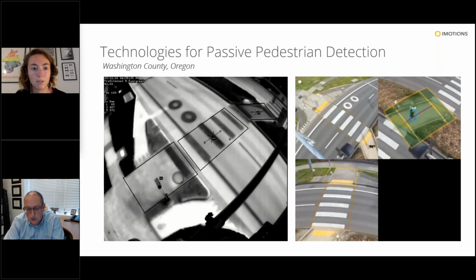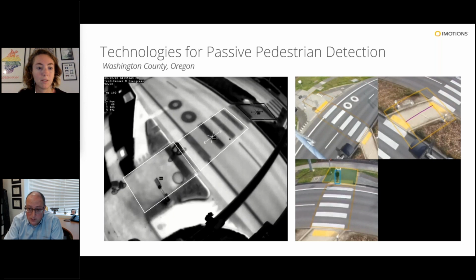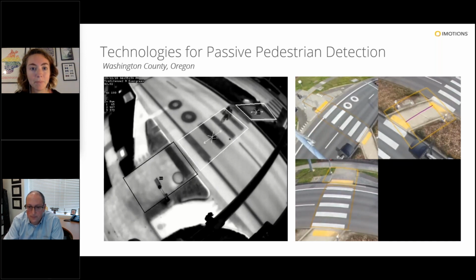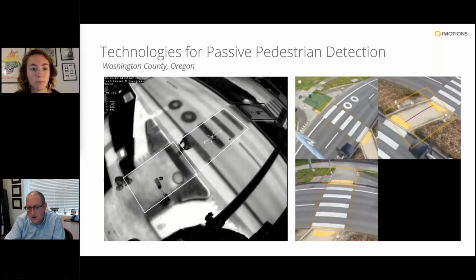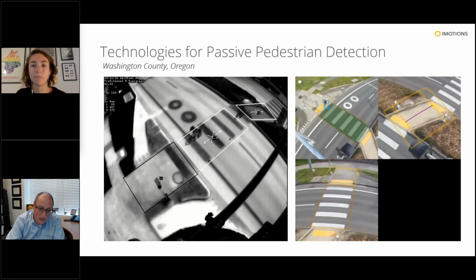So you could imagine a scenario where a ped or a bike perhaps pushes a push button, placing a call for service on the system, then sees a gap in the conflicting stream of traffic and maybe jaywalks, maybe crosses against the pedestrian signal. In those situations, if we can track them all the way across the roadway, we can then drop that call for service and prevent our vehicles from being stopped for what some people would call a ghost pedestrian phase. And so that's one use case.